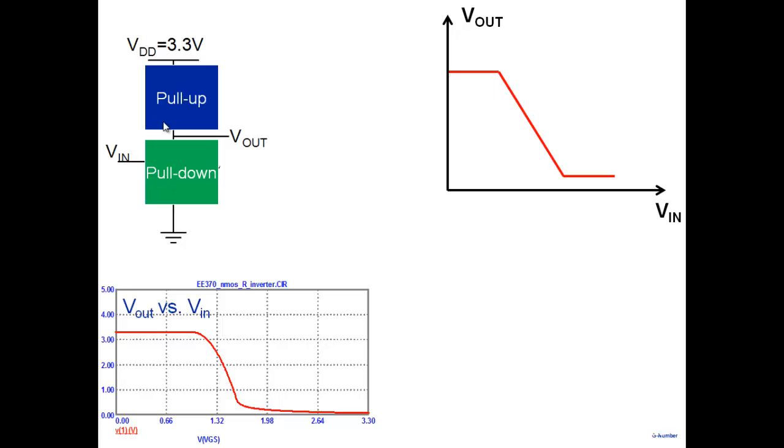Right now, if it's a pull up and a pull down device, let's say it has a VTC like this. Now note that pull up will have some resistance and pull down will have some resistance here. Now I want this VTC to be shifted towards the right. What do you have to do? Can you all see that I will have to decrease the pull up resistance? One way of shifting it towards the right. Whatever is the device, I have to reduce this resistance to shift it towards the right. This is an important point.